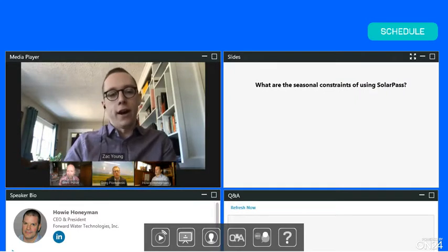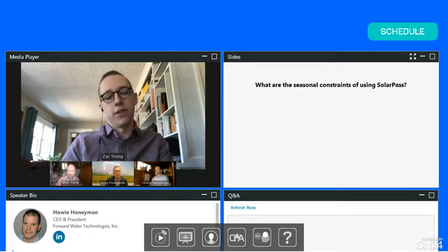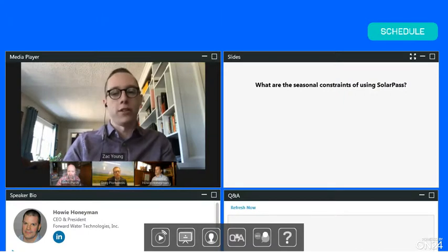It just changes the relative throughput of the system, where we're, as you would have seen in some of my figures there, measuring on an accumulated UV dose. So where you have lower UV intensity or lower number of hours of sunlight a day, it would affect the overall throughput of the system, though we find that the process is pretty well aligned with the received UV, and so it turns up and turns down appropriately. And in fact, that's a part of our process design as well, being able to monitor, predict, and confirm the requisite dose of UV as we go through the process on a day-to-day, week-to-week, and seasonal basis.